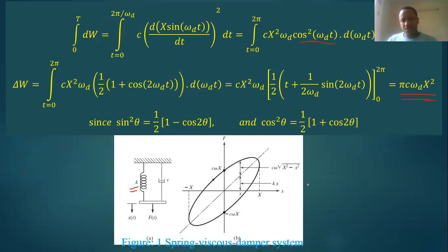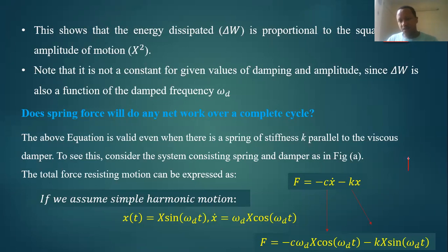When we cut it from here, we have a spring part, the K part, and there is a system which is subjected to some external force F. Considering this axis as positive, F is equal to minus C x dot minus Kx. So this is the force.